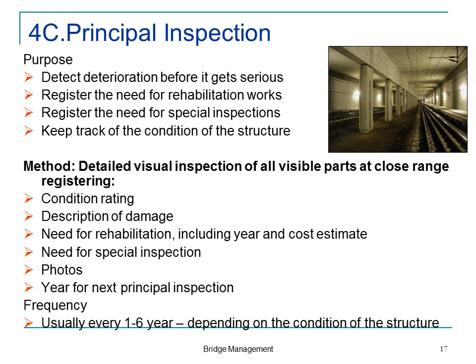In the principal inspections, we need more physical access. We need to be able to get really close to the structure, because it can be very difficult to see the damages if you are 5, 10 or 50 meters away. We describe the damage we have seen.